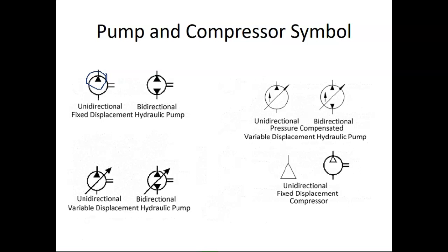The direction of that triangle. Okay, if it's a pump or compressor, it's going to face out. If it's a motor, which way does it face? Inward. Think about how they work differently. A pump and compressor are pushing fluid into the system, yeah? That makes sense? A motor is pulling fluid from the system to run. That make sense to you all?